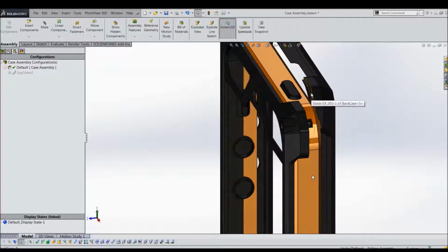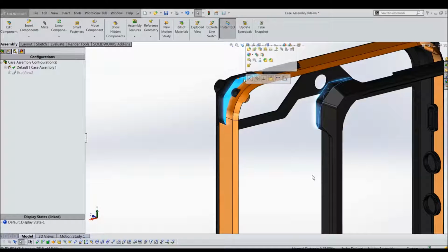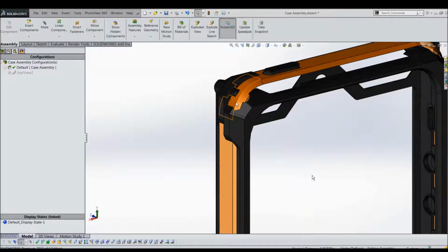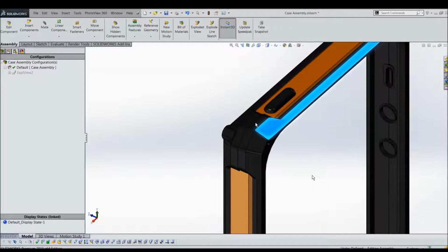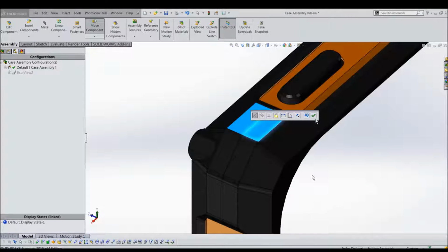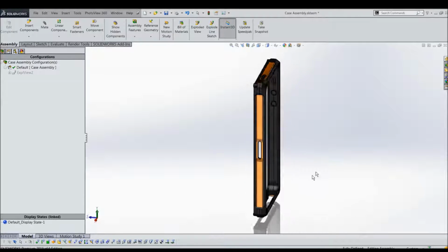To precisely place the parts, we need to use the mate function to fully constrain the new part with the existing model. The Quick Mate feature allows me to directly select the corresponding faces, and the available mate options will just pop up and be applied.